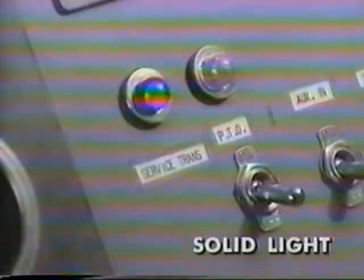Now turn the key on. The service transmission light should go on. If it doesn't, replace the light and retest. If the problem persists, repair or replace the vehicle interface harness. If you go through the checks and nothing's wrong, something's wrong with the ECU circuitry. You'll need to replace the shift bar cover.